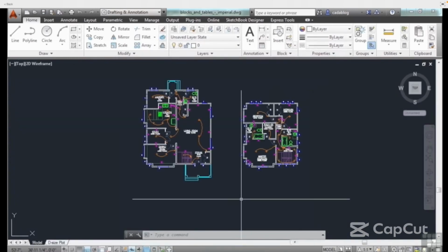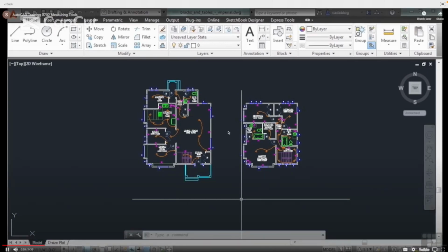There are several different ways and methods that you can list out the properties of the data or line work in your file. One way is to use the properties palette, as we've seen in other chapters already. That's great for one object at a time, but it can be overwhelming because the amount of information the properties palette shows you is, well, everything. So there is a feature that you can use that's called Quick Properties.